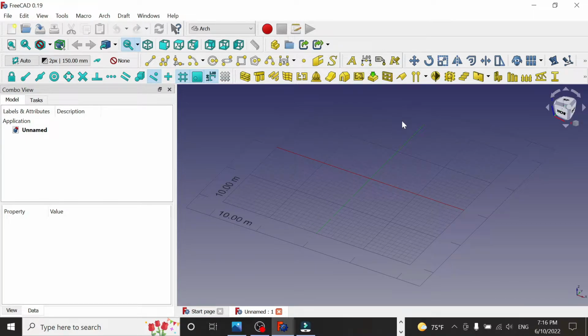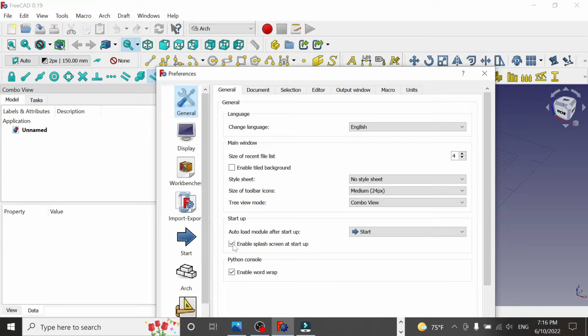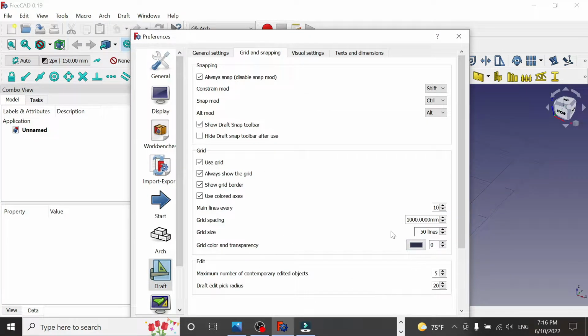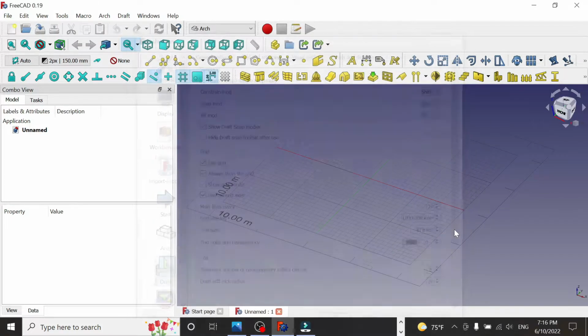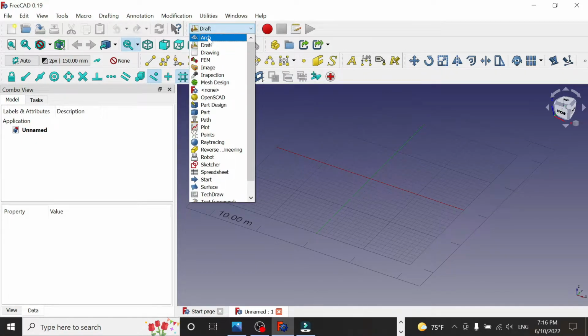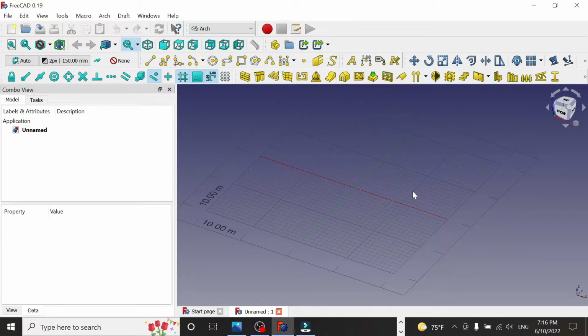So the system is not going to accept an odd number, only an even number, 40 or 60. So let's put the correct number here. Let's put 40, so we don't confuse the system. And now it's correct. Now our grid is 40 by 40 meters and our building is going to be somewhere here.